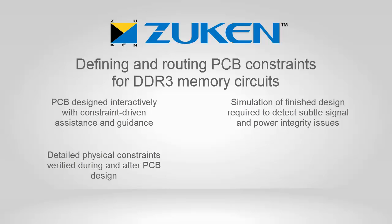Notice how applying topology templates and even plain copy and paste made it much easier to design this circuit with maximum electrical symmetry. DDR3 uses source synchronous logic, and that means maximum electrical symmetry yields maximum performance at the highest clock rates.